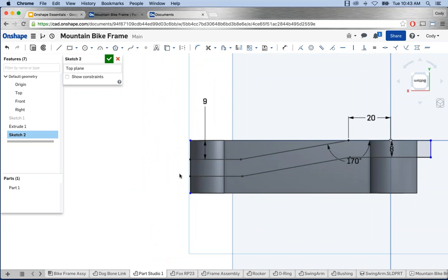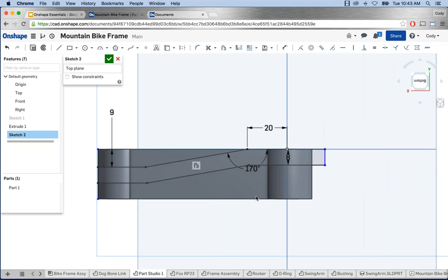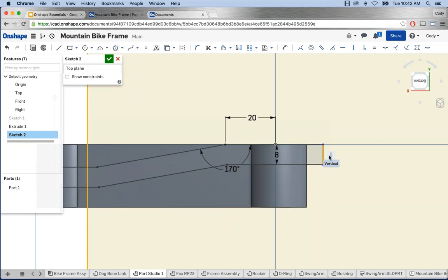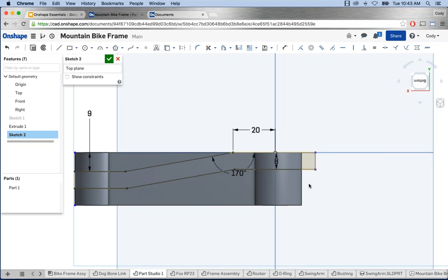Now, you may ask, well, why all the effort? Why even bother? Just leave it out, extend it out in space. The benefit of this is it will update if you change the model later. If I made this model longer, or changed the radius or whatever it was, because it's constrained or attached to the radius edge, it will update. If I just simply left it extending out like I do here, if the model changes, this may not update. It will not update the way I'd expect, right? So it's more about design intent.